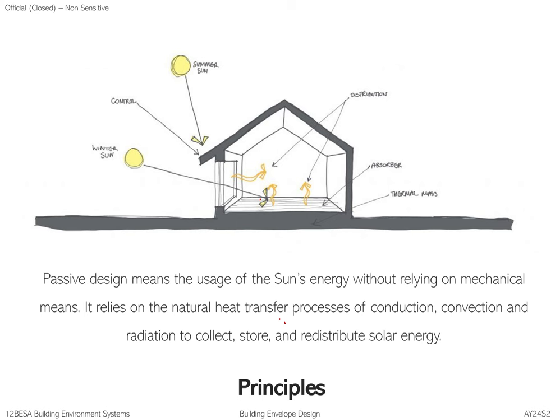So in summer, when it's very hot, of course you will want as little sun as possible to enter the interior spaces. You want to exclude as much as possible, right? So one of the passive strategies that we have is a pitch roof, whereby the highest point is actually not habitable, because hot air rises. So hot air rises, collects there, and usually there's some outlet for the hot air to go out, right? But most of the summer sun is excluded in this case.